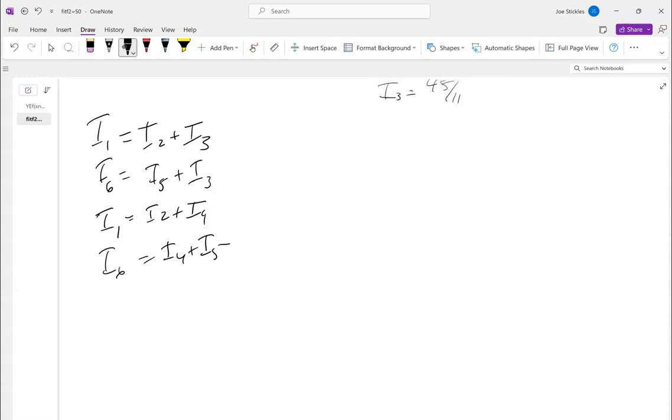Okay. Now let's go around the circuits and make our equations looking at voltage gains and voltage drops, right? So they've got the battery set up for you. We'll just use the orientation where they've got the batteries pointed for us for that first one on the left. So we'll go around it counterclockwise. What voltage drop do you have if I go around counterclockwise this way? 10I1, right?